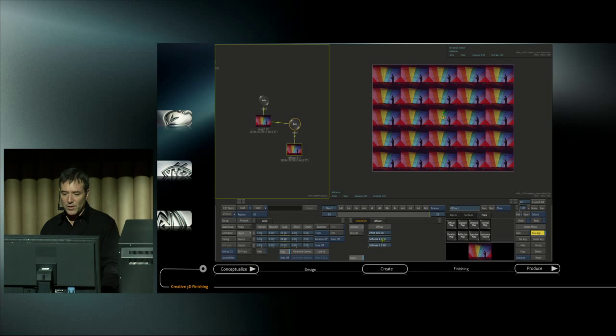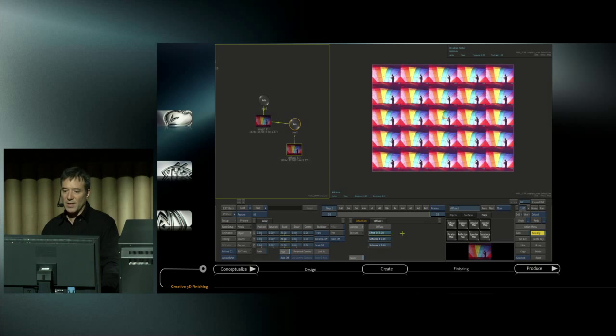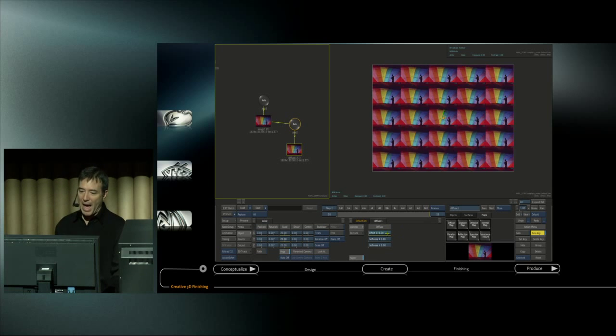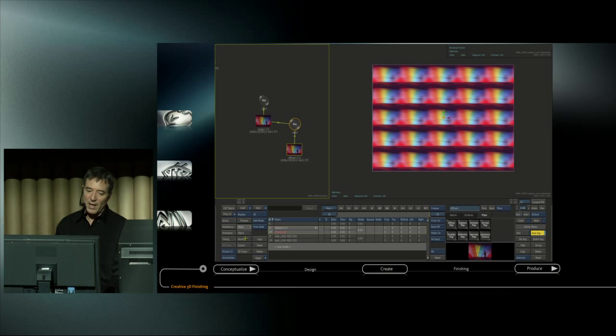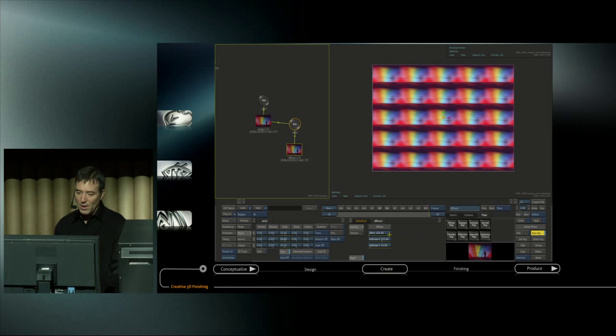But notice if I go back to the controls, I have the ability to adjust the gain on any of these maps. And again, we're doing that gain across multiple tiles all at the same time. And if I adjust the softness, same thing. And these are based on the GPU performance, so that scales a lot faster and better than the CPU performance, which is the way we were doing blurs before when we were tying them to the media layers. So CPU versus GPU, GPU is always going to be preferred. So again, you can see that we're now taking advantage of that commodity hardware to deliver better performance for things like blurs. And again, it's a quality issue as well.